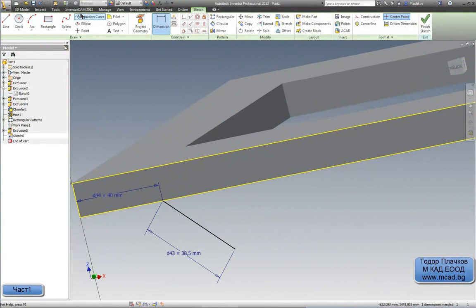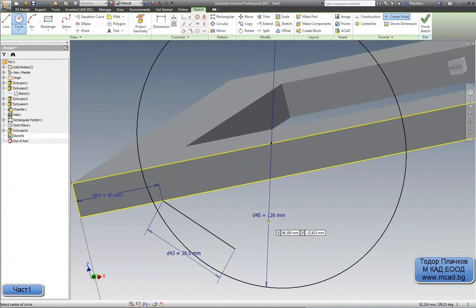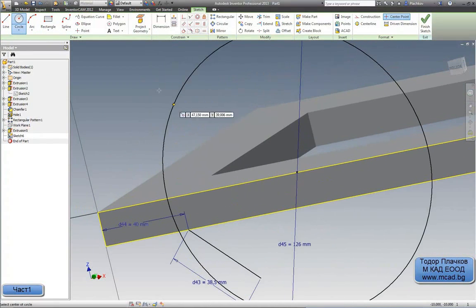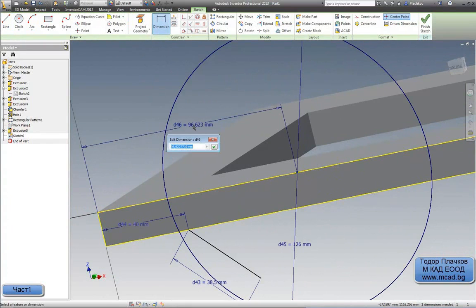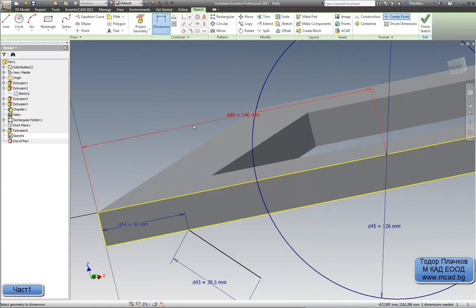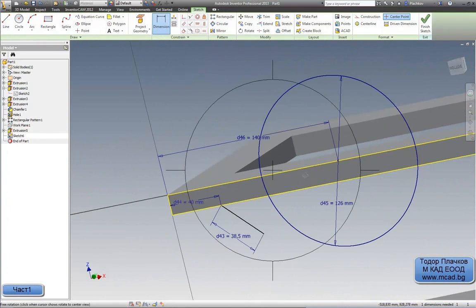If you have a correct and precise DWG, use it. Don't do it like I am doing right now, measuring all the geometries I have in the DWG. Copy and paste, that's the way, or insert with the AutoCAD command, which is in the upper right of the ribbon menu.